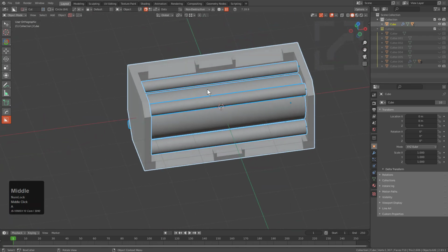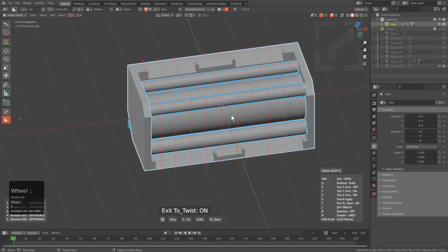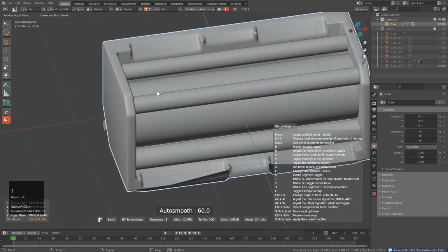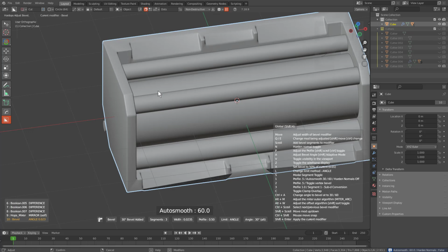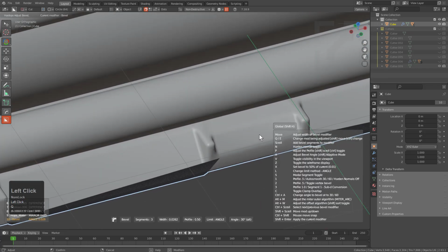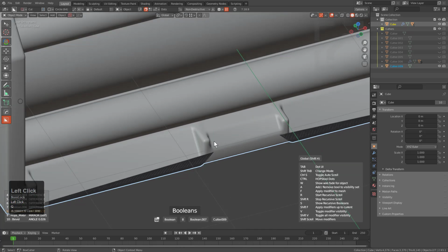But now with this all selected, we could just press Q, go under dice, and choose to dice. But if we press T to twist, we already know that it's going to trigger the behavior of join and smart apply prior to us having to do this. And there really isn't very complex of modifiers happening with this. So to really make things more interesting, let's put a bevel on this, which anytime you put bevel, it's going to cause you to reevaluate some of your cuts and geometry. That's just the way bevel is.